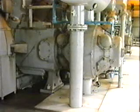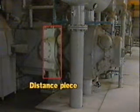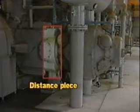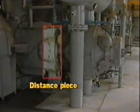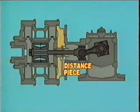Between the crosshead bed section and the cylinder is the distance piece. This is where you'll find the wiper rings and pressure packing. The distance piece prevents any processed gas from leaking into the crankcase and provides a way to vent any leaking gas away from the compressor.